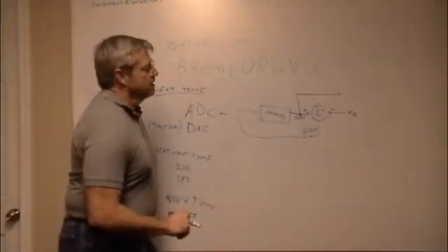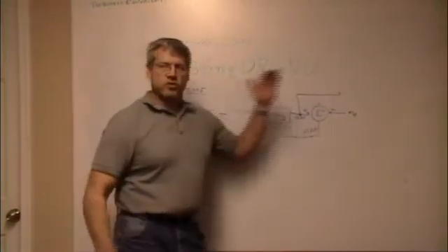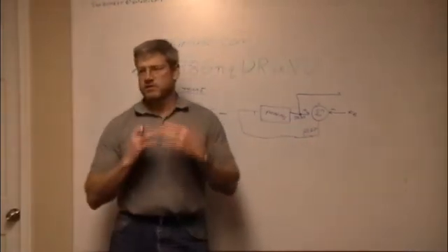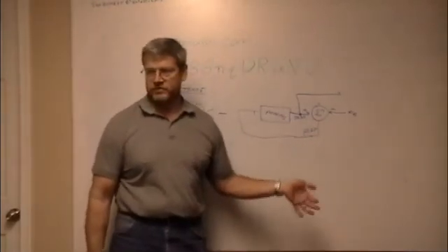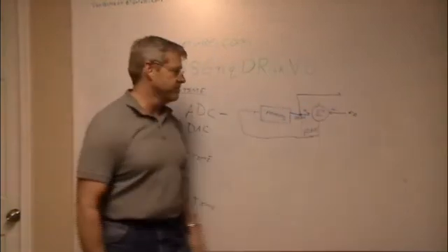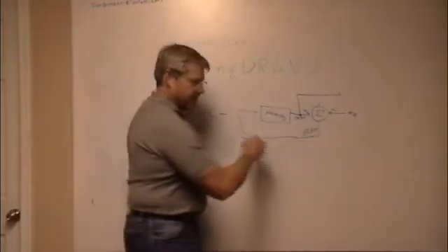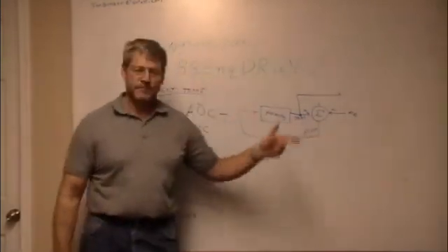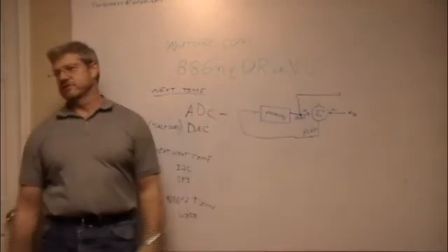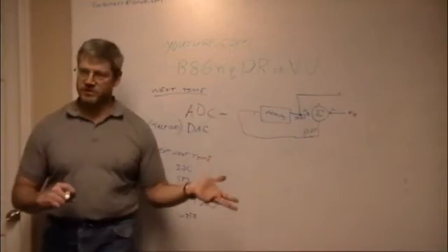And so what you're controlling is temperature. You're pushing a signal out to control temperature, and your system can only turn on or off. So this is going to be on, off, or PWM at some rate to keep you where you want to be. The feedback is going to be the actual temperature. You get an error value that comes back and you act on the error. If you're exactly on, the error is 0, you do nothing. You sit there. But as soon as the error starts to grow, then you start to do things.